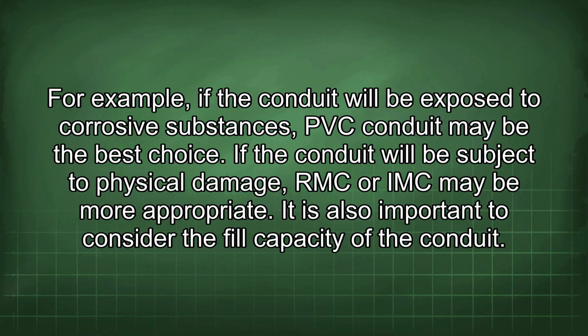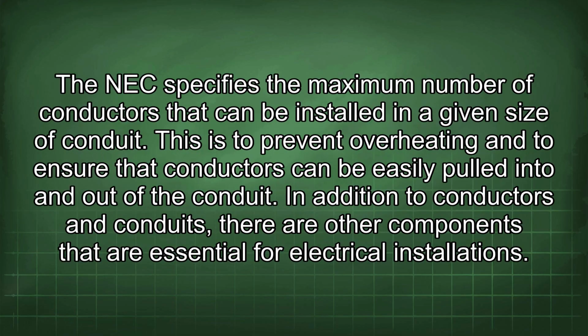It is also important to consider the fill capacity of the conduit. The NEC specifies the maximum number of conductors that can be installed in a given size of conduit. This is to prevent overheating and to ensure that conductors can be easily pulled into and out of the conduit.